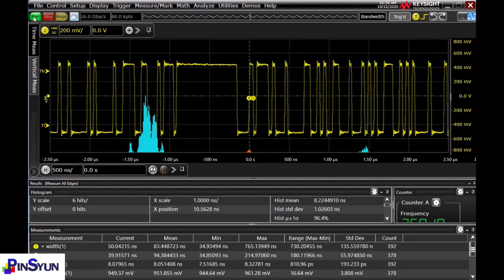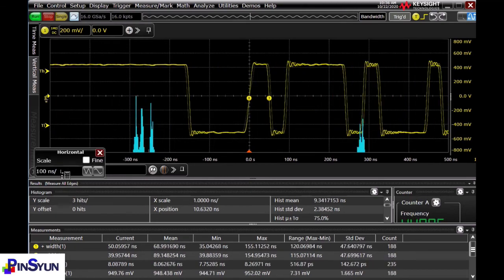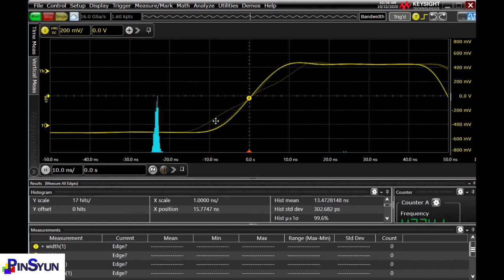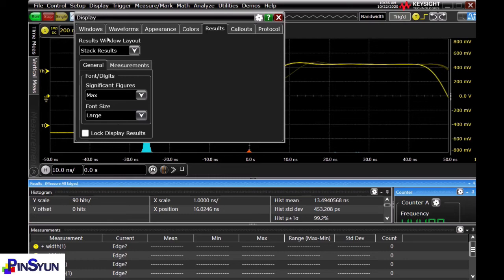And what's the benefit of triggering on the glitch and of the fault here? So if I click run and start running the scope again and zoom back in, you can see now I'm only exclusively triggering on slow rising edges. Now, to jump essentially back into demo 3 for a second, we can actually control the counter to see how often this slow rising edge is happening.